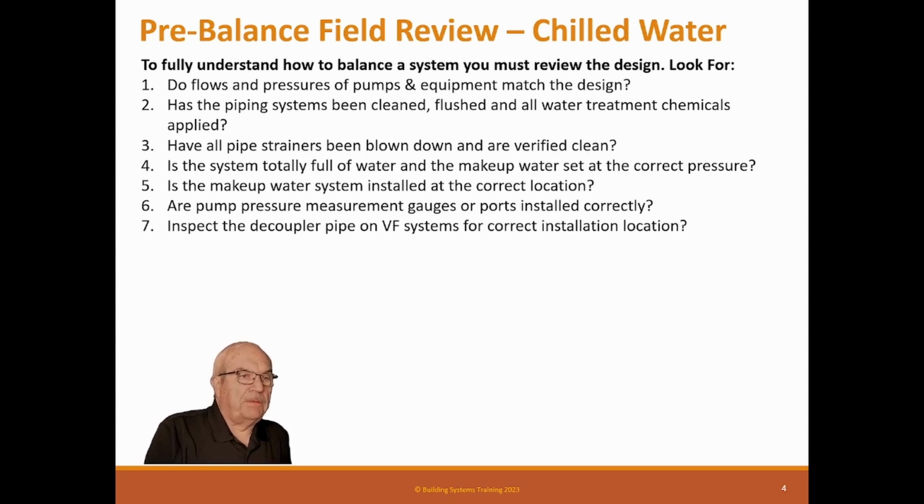Inspect the decoupler pipe on the variable flow system for correct installation location. Now, we'll talk about the decoupler, but if the decoupler is installed in the wrong place, the system will not flow the right amount of water. And we find these installed wrong about 30% of the time.